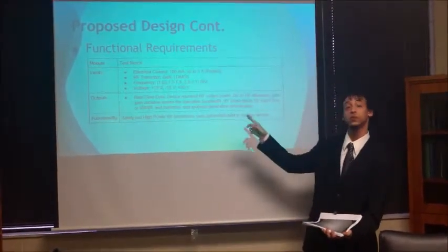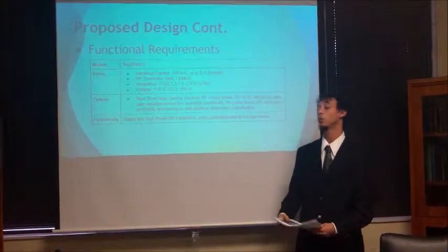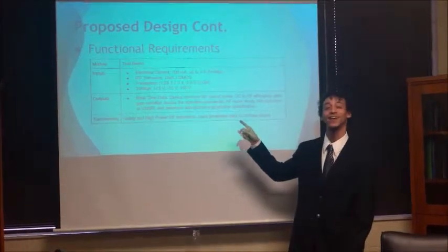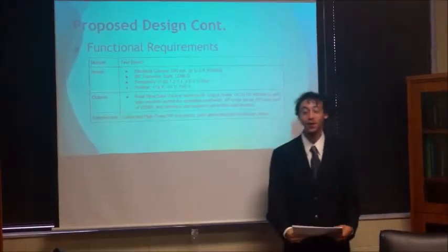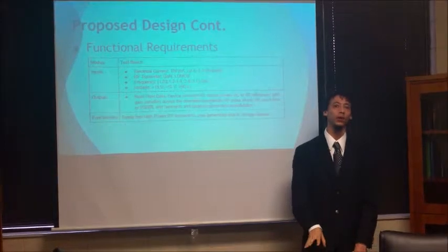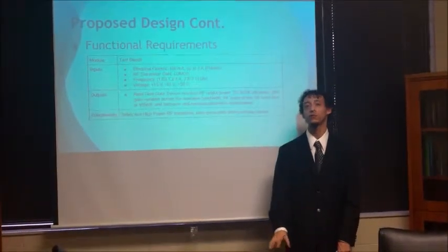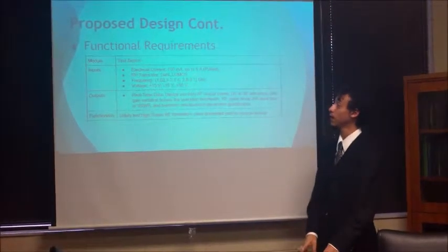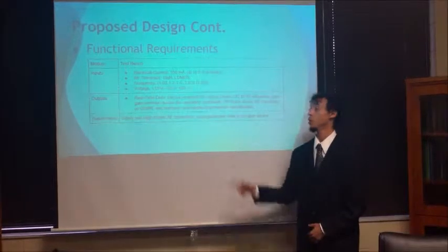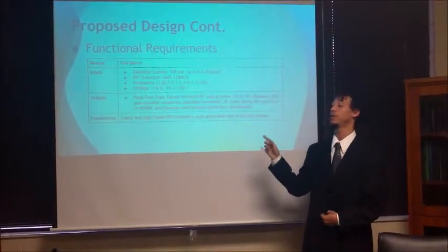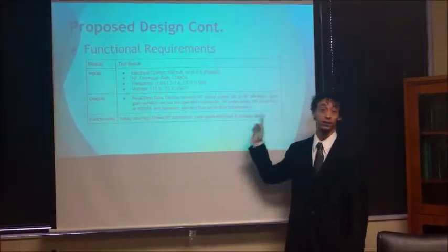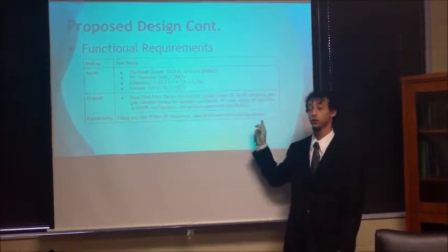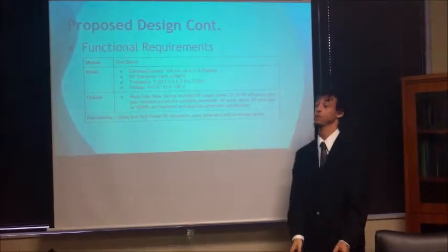And the frequency ranges we'll be looking for will be 1.03, 1.2 to 1.4 gigahertz, and 2.8 to 3.1 gigahertz. For our voltage input we'll be looking for 15 volts, minus 15 volts, and positive 50 volts. Now the output will provide a lot of real-time data to the computer. We'll be monitoring the RF output power, DC to RF efficiency, gain variation, RF pulse width, input loss, and the harmonic and spurious generation specification.